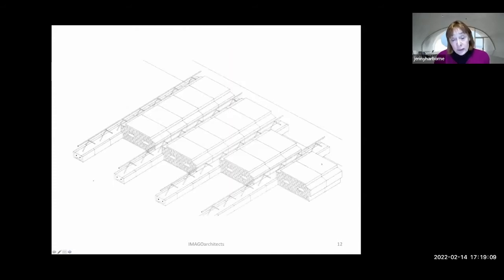This is a really good product, which I wish we could get here easily. It's equivalent to the pot and beam floor, but just with clay blocks. These are all really lightweight blocks that you just pop together between a beam made of the lintel blocks with some reinforcement steels and concrete to form the beams. And then you'd have a really lightweight, solid, warm floor.